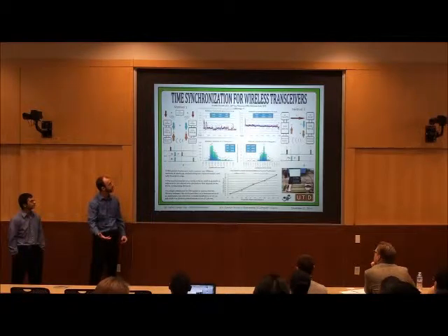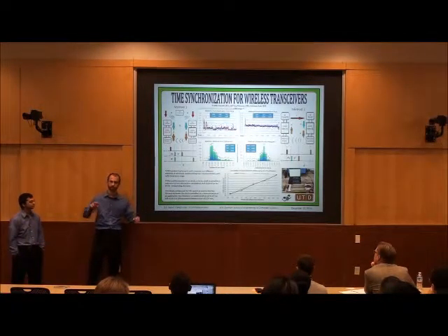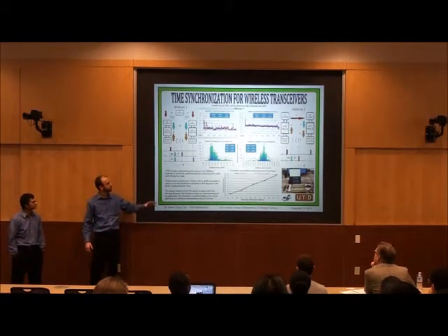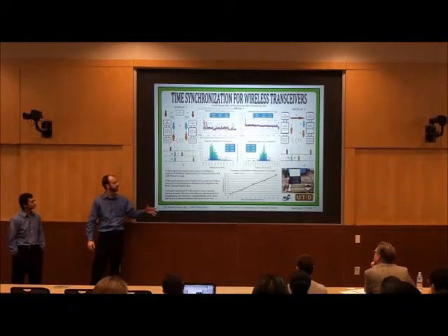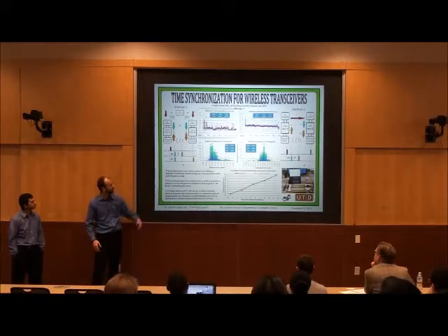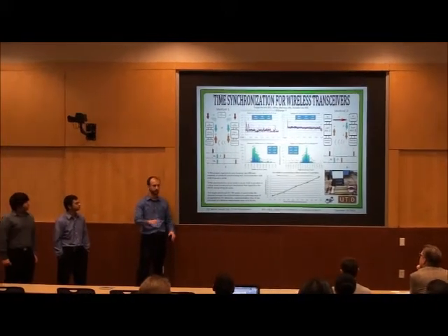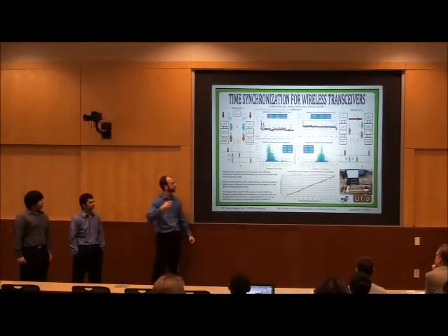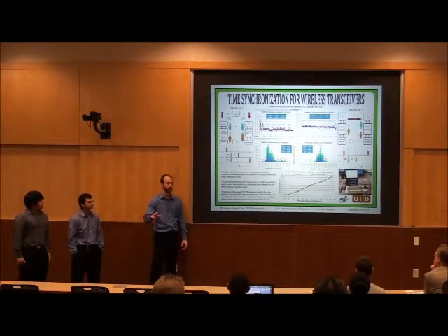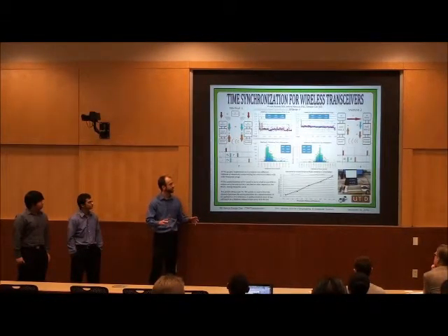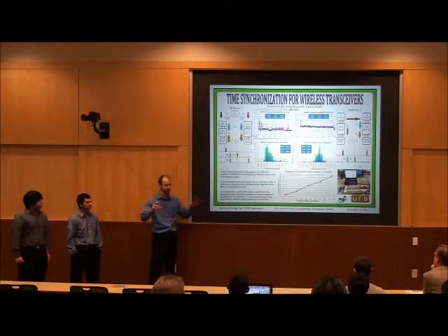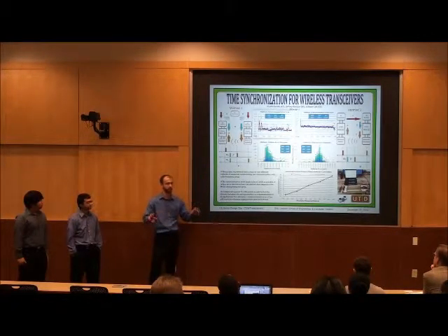Going on to method two, we have one RF transmitter and one RF receiver. The first microcontroller transmits the beam to be sent to the second one, which picks it up and it's received at time two, which is the average time over a large set of trials. That's going to be a constant for the receiver, the average. The synchronization error for that one is going to be each individual received time minus the average time. And for the first one, it's going to be the two individual received times, alpha 1 minus alpha 2.